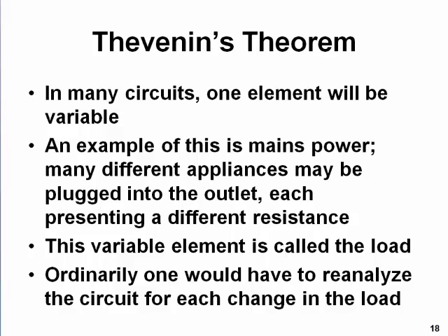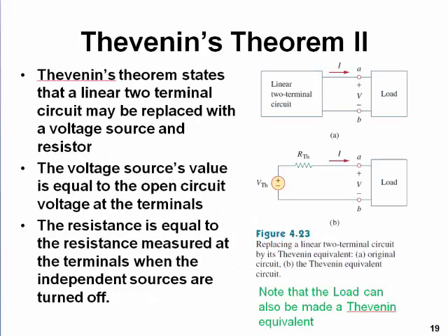You can also think of a lot of other things, circuits that turn off and turn on, or circuits that start processing something. For example, in making this video, my computer is working harder and dissipating more power, so this is a variable load. So we want to model the source as one source and understand how it will behave with a bunch of different loads, not have to reanalyze the circuit over and over again. So that's what we use Thevenin's for.